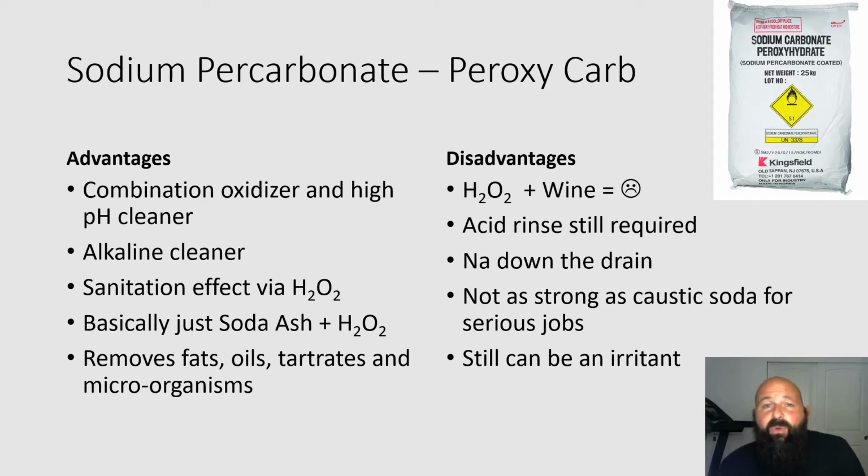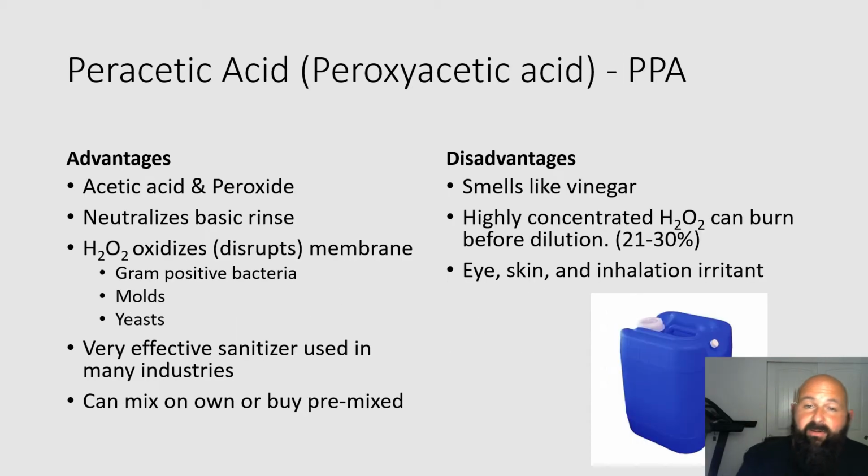Downside is, again, we're throwing some sodium down the drain. Now if you're on an evaporation pond, probably not such a big deal, but if you're going to be recycling your water for irrigation, that sodium can become an issue for soil aggregation. So other things are, it's not as strong as caustic soda, and if you tend to have sensitive skin, it certainly can be an irritant.